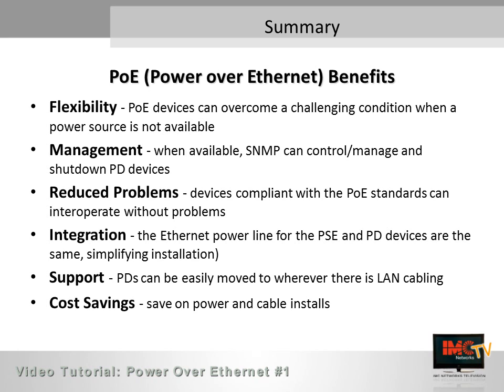In summary, PoE offers a host of benefits. The first, of course, is flexibility, because the PoE devices can overcome a challenging condition when a power source is not available. Management, when available, is also useful because you can control, manage, or shut down PD devices, for example, like the IE Mini FiberLinks 2. There certainly would be a reduction of problems because all PoE devices have to meet the 802.3 standard, and interoperability becomes very easy to support.